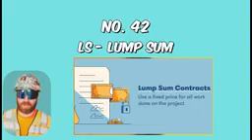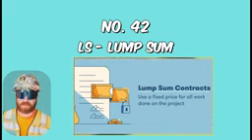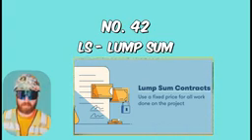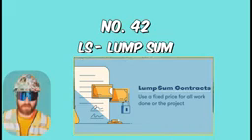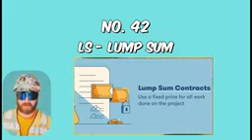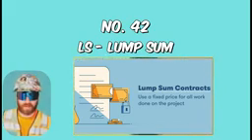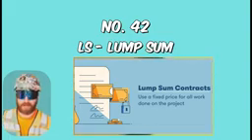LS, or lump sum. GMP, or guaranteed maximum price, can generate cost savings to the owner if the construction team didn't utilize the entire budget throughout the project. LS, or lump sum, is usually referred to as hard bid, where the upfront price doesn't necessarily show as much backup as you would see in a GMP estimate, but the contractor doesn't provide any credit or money back at the end of the project.